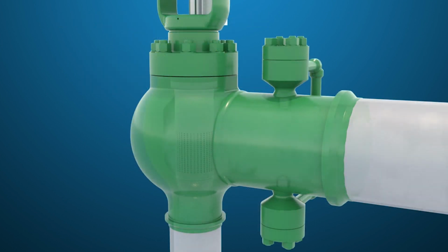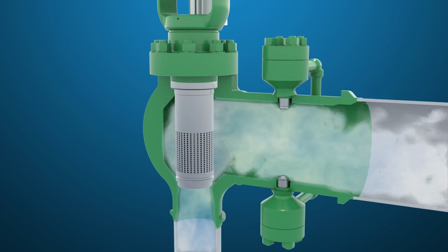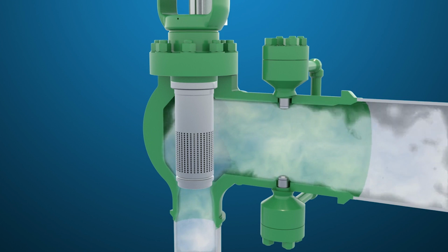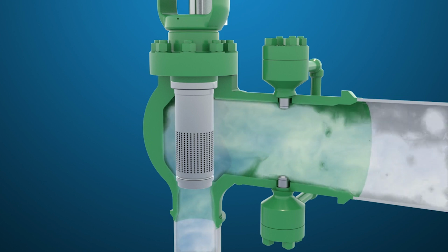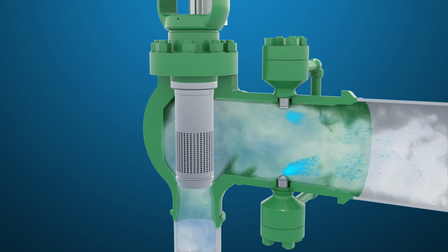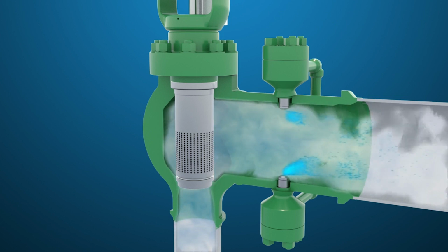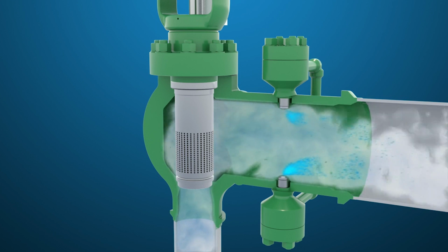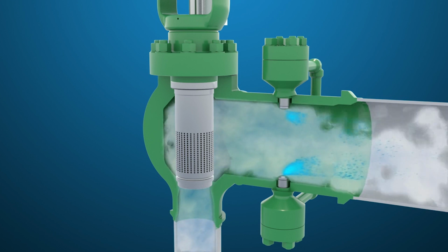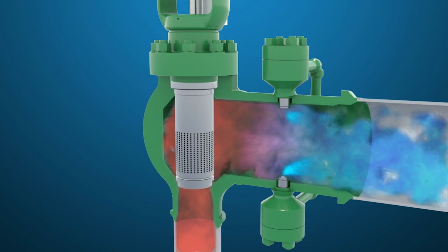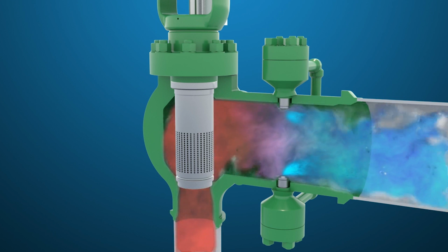The de-superheating section is used to condition the steam exiting the bypass valve to meet the requirements of the downstream system. Feed water is supplied to nozzles via a spray valve and associated block valve, spraying the water into the steam flow path. The water injected into the steam evaporates by absorbing heat from the superheated steam. The result is a reduced steam temperature.